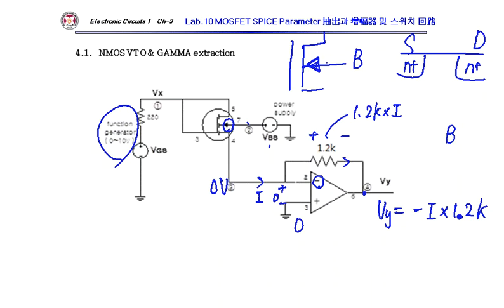It says if the bulk is forward biased, current will flow that way. So this arrow represents that I have a P-type substrate, a P-type bulk. For the P-type bulk, it's an N-channel MOSFET. So this should be the most negative potential in the circuit, which is 0, right?